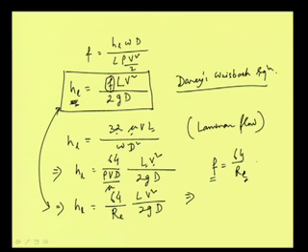So, in laminar flow it is not influenced by the frictional roughness of the pipe, which we did discuss earlier in the last class. The same thing we can establish from this relation, that it is related only to the Reynolds number. The frictional roughness of the pipe boundary is not coming in. So, we can write F is equal to 64 by Re, it is thus inversely proportional.